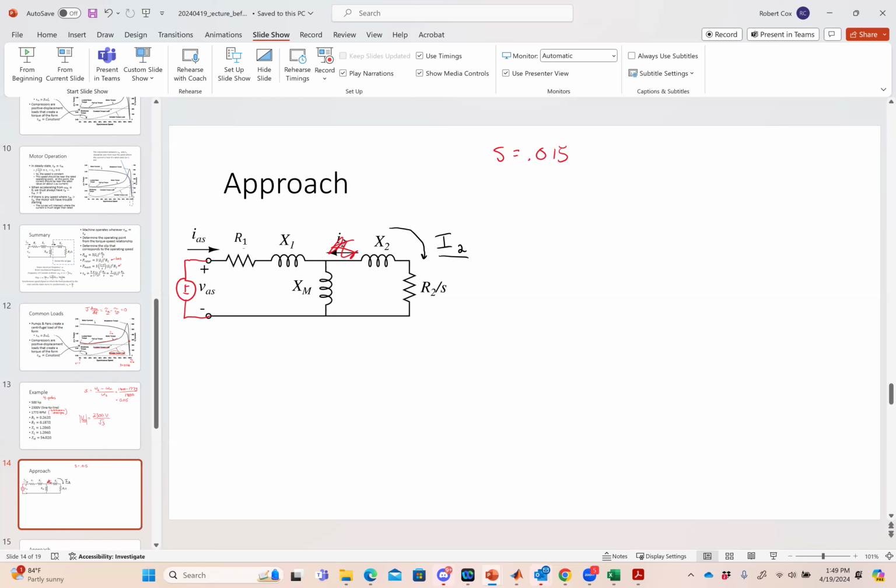Define the total resistance, define the total current, and do current division. Find the total impedance and do current division. I like you. You're my kind of guy. I was hoping you weren't going to tell me do mesh or nodal. That's good. I like current division better. All right. So what's the total impedance? Not R1 plus X1. Close. Not R1 plus X1. Plus JX1. There you go. R1 plus JX1.